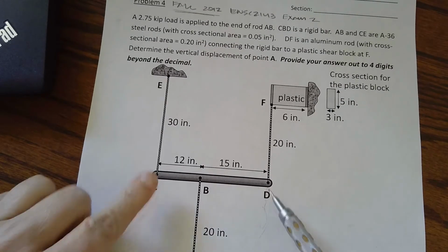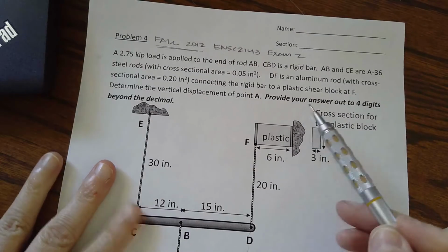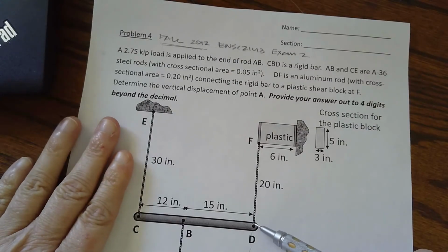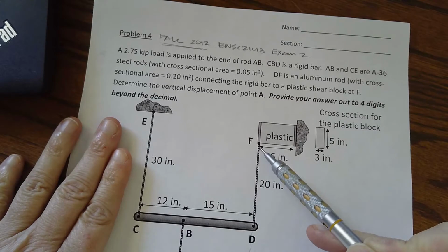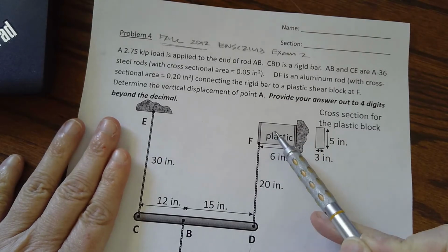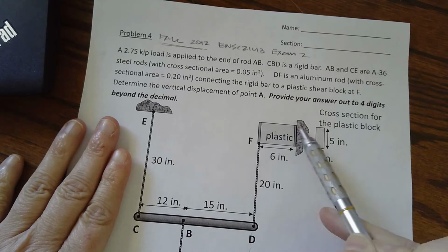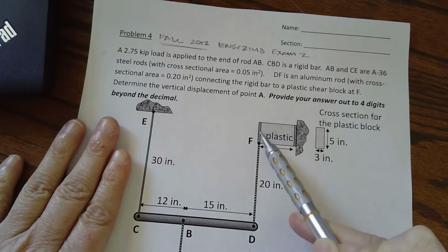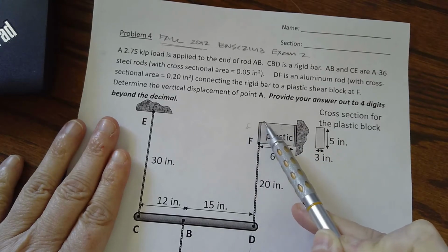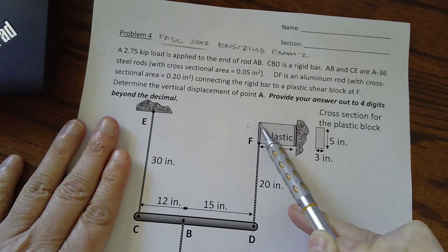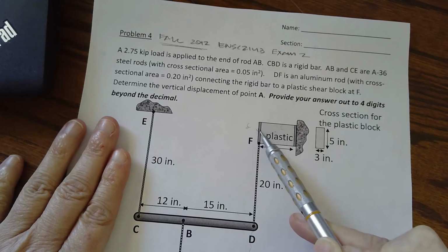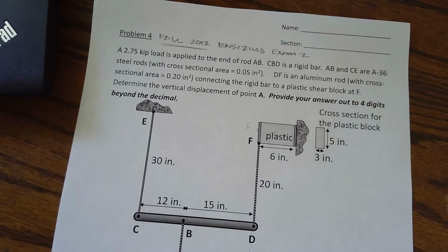We'll have to figure out if it comes straight down or rotates. As we apply a force here and get this force in cable DF, we're going to cause our shear block to skew. When it begins to skew, it's going to have that shear strain, which is going to result in a delta as this point here comes down because of the shear force acting on the block.